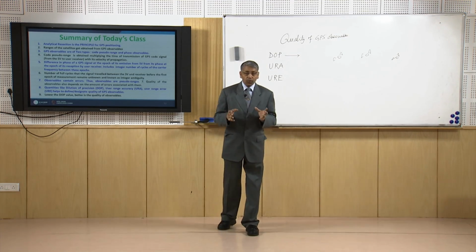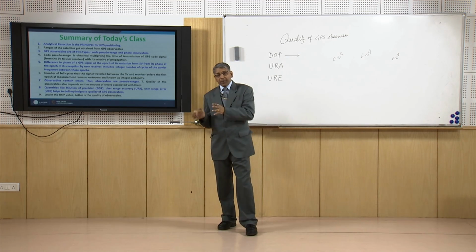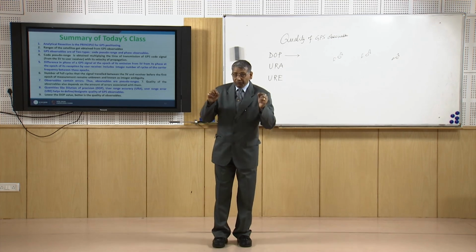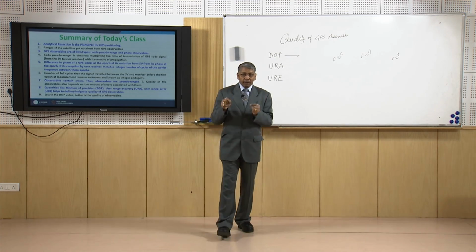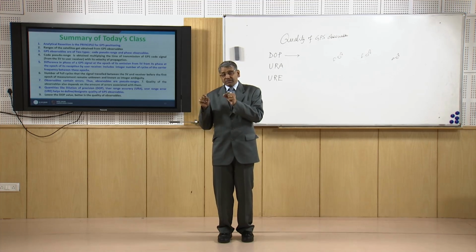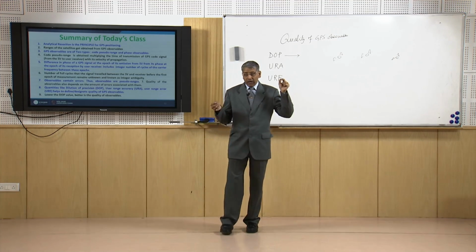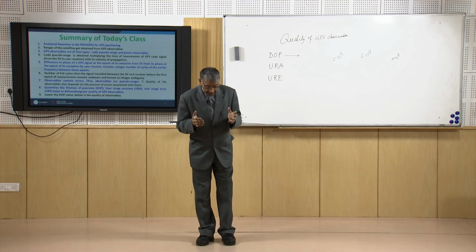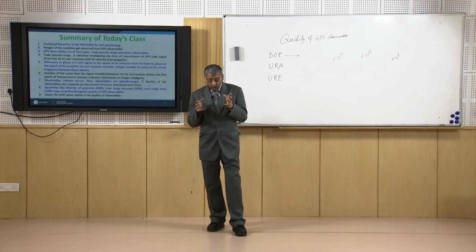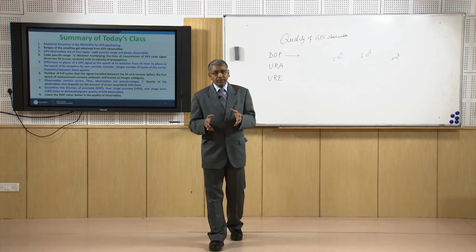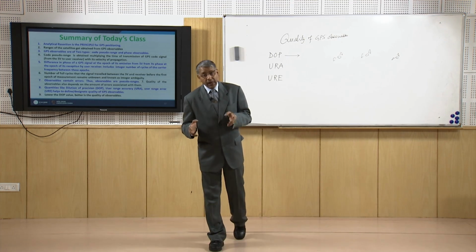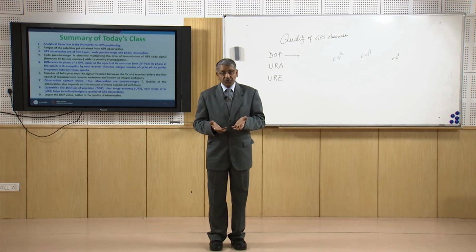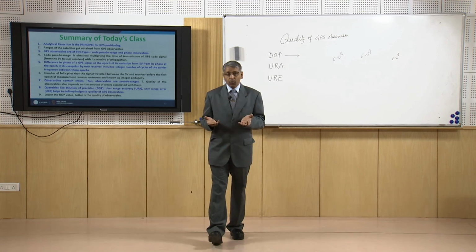Actually in GPS observable we get the phase of the GPS signal, and if we multiply that phase observable by the wavelength of the signal, that will provide us the carrier pseudo range. The position from GPS observable depends upon the quality of the GPS observable, and the quality depends upon the amount of error associated with it: the lesser the error, the better the quality.